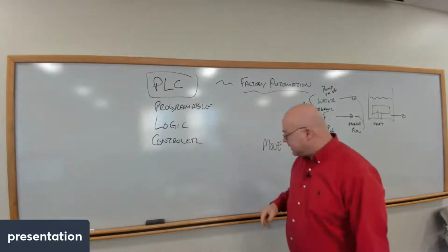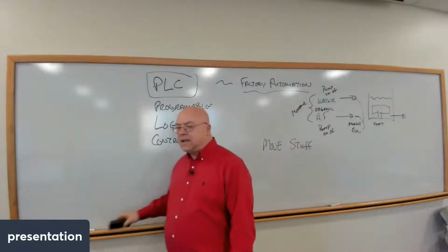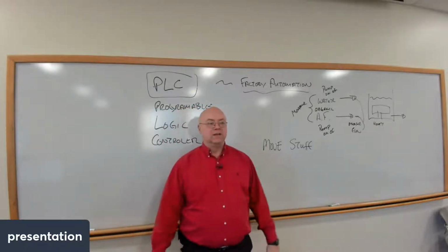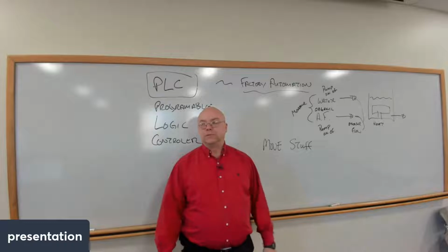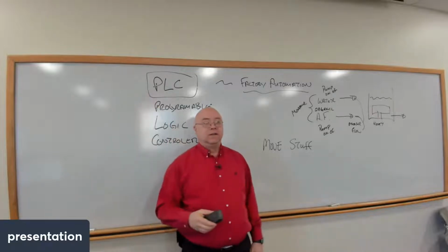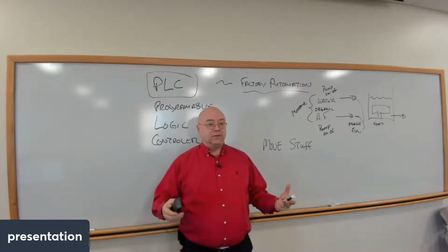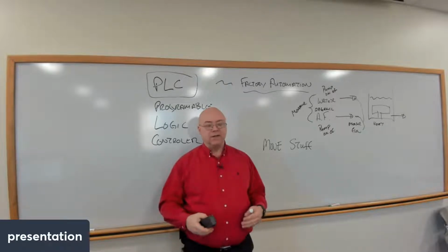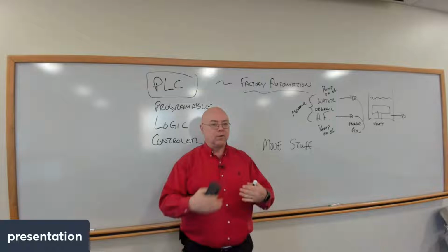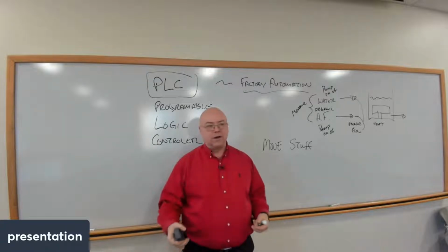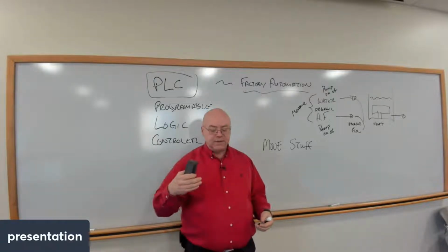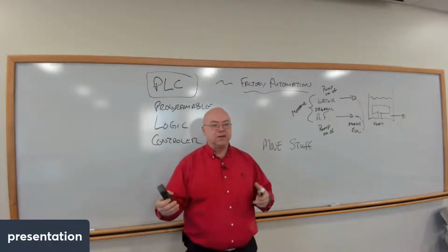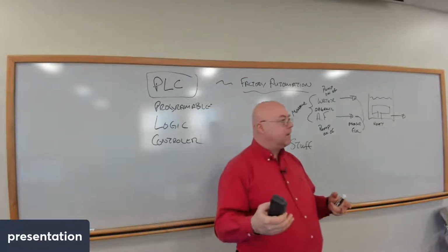This ladder logic, and you say, but why don't we just use a PC today, right? Because we can do the same kind of thing. So PLCs, and you can, right? You can put I/O cards in your PC. You can have an industrial PC that has all these I/O cards, and you can run Windows on it, and you can have this input output and do the math and decide when to control things.